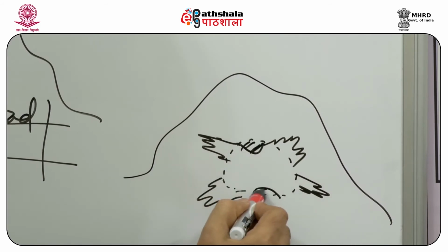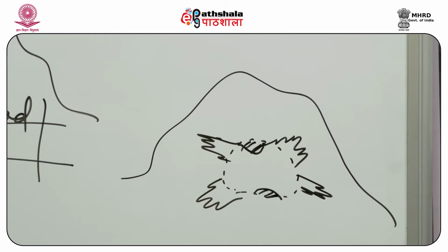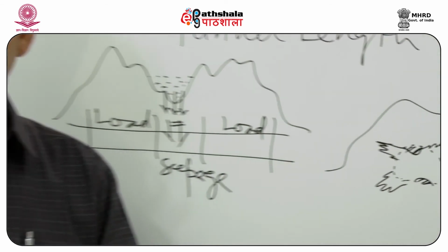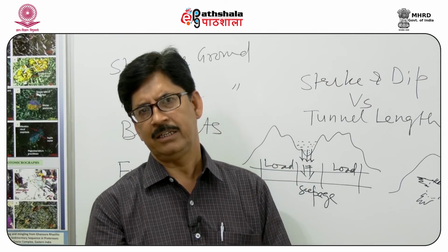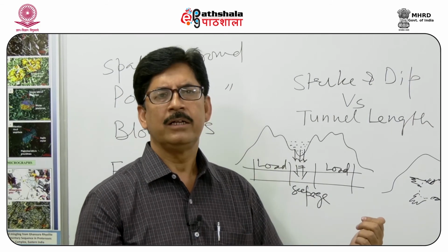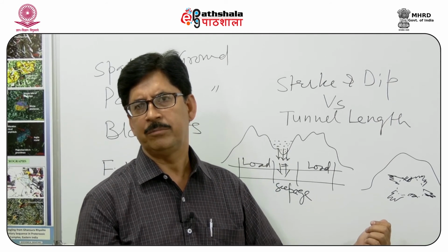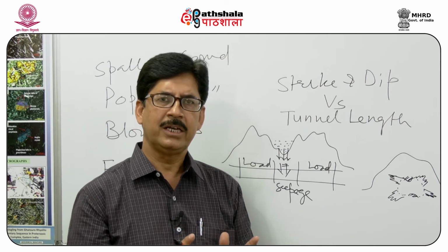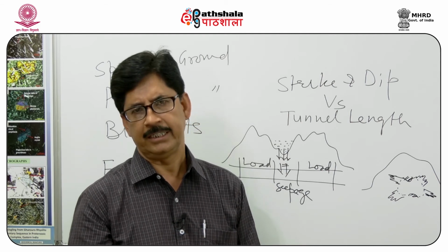Both of these issues are not desired, because if you have overbreak, then you have to backfill with concrete up to the required diameter, which is called the pay line, and which will incur extra cost. If you have underbreak, then you have to excavate again by some method. So this problem of overbreak and underbreak has to be resolved, and the pay line has to be decided.